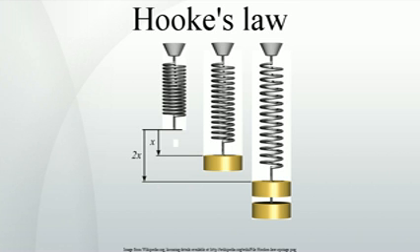An elastic body or material for which this equation can be assumed is said to be linear elastic or Hookean. Hooke's law is only a first-order linear approximation to the real response of springs and other elastic bodies to applied forces. It must eventually fail once the forces exceed some limit, since no material can be compressed beyond a certain minimum size, or stretched beyond a maximum size, without some permanent deformation or change of state.